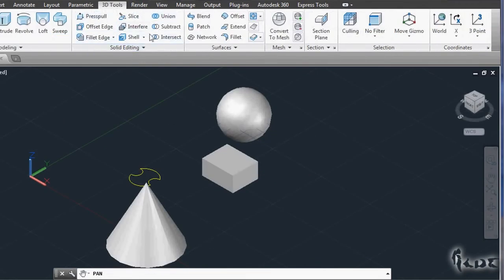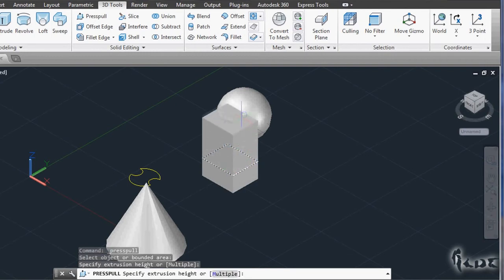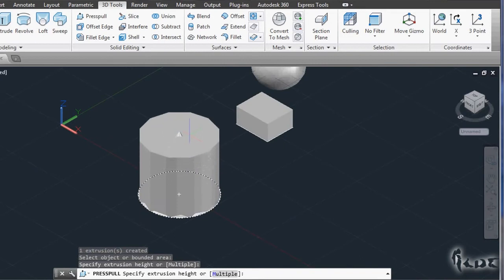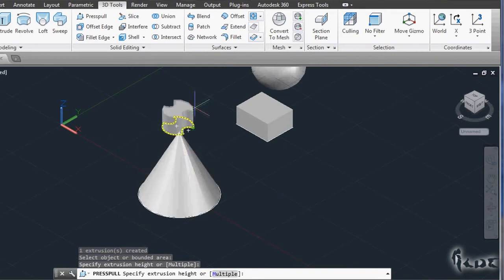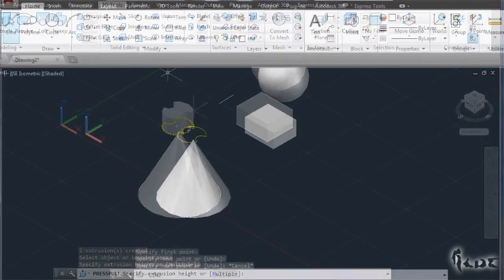You can edit your 3D objects at a more advanced level in the 3D window, under the Solid Editing section. Press Pull simply pulls up a surface, giving height to it according to its base. This does work on 2D faces, and so on 2D flat objects as well.